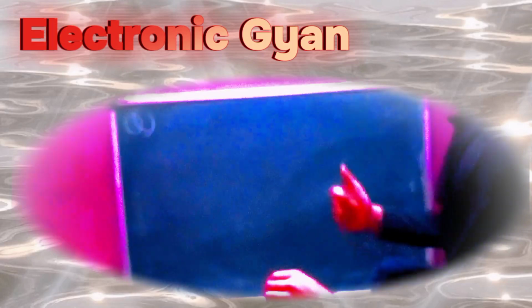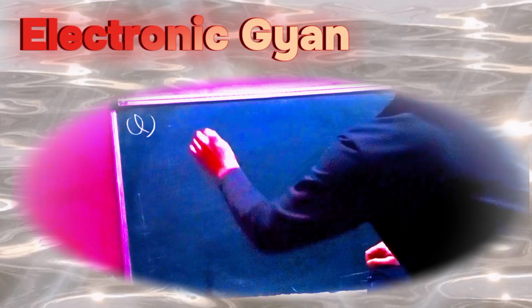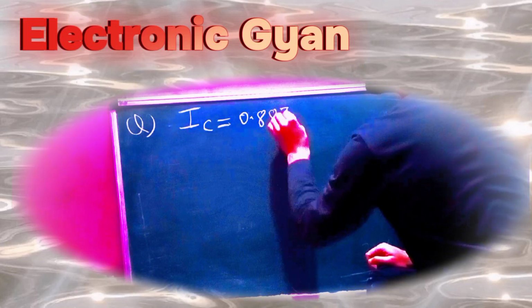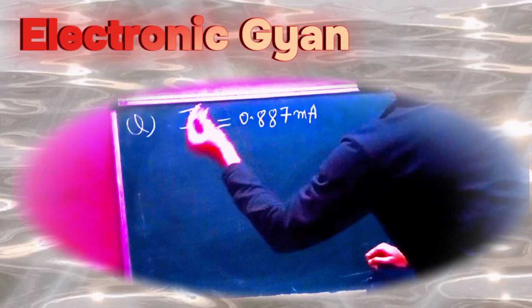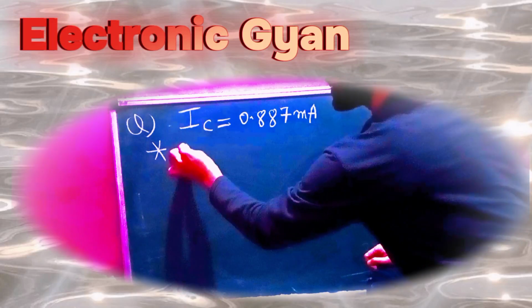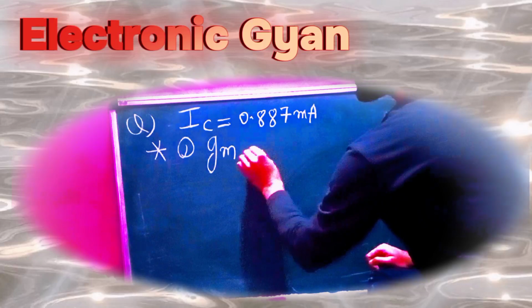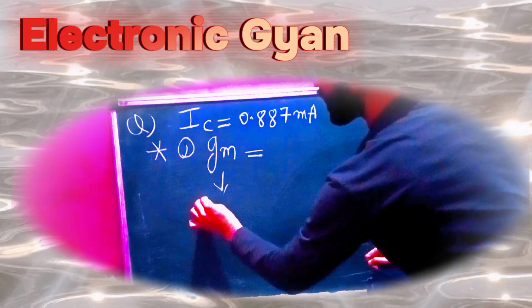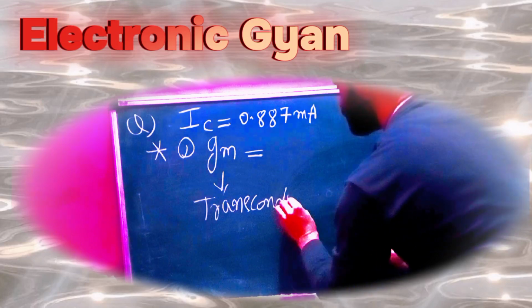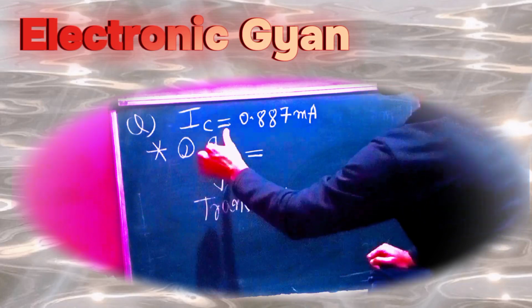Before going to the small signal analysis, we are going to find the small signal parameters of the common emitter amplifier with the help of the obtained collector current. So the obtained collector current, how much have we obtained? That is 0.887 milliampere. What is the main important small signal parameter of the common emitter amplifier? First is the transconductance of an amplifier, which is represented by Gm. So this Gm is nothing but transconductance.